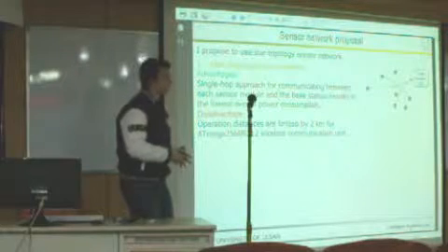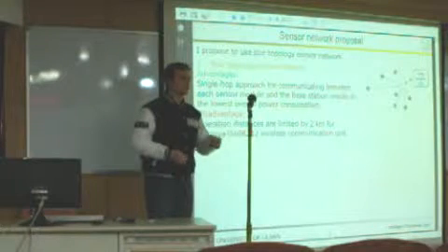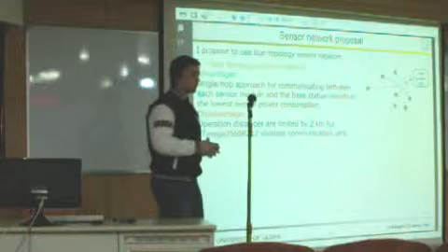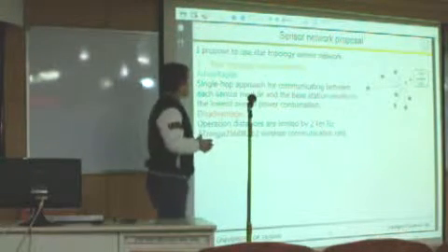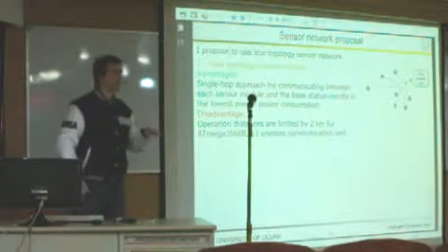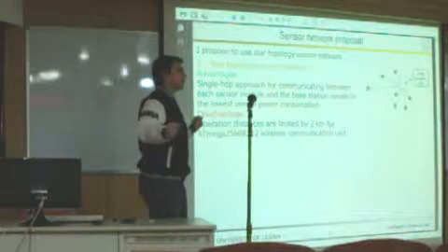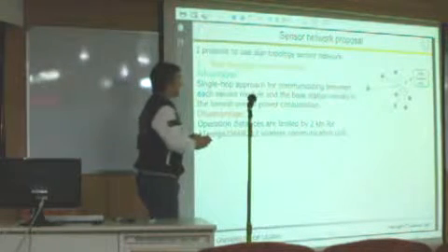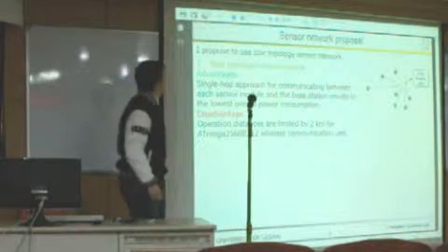In order to use these transceivers, we had to use 900 megahertz. But in Korea, we cannot use this frequency without a band license. So if we cannot use this frequency, we should use 2.4 gigahertz transceivers, but the operation range is maybe 100 meters and no more. If we can buy a license, we can use this topology network.